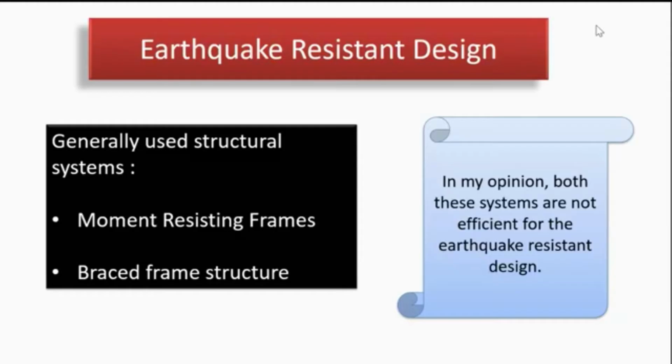But when we are designing the braced frame structure, the bracing we consider in the analysis has substantially different capacity in compression and tension. A member resisting tension in one earthquake cycle will have compression in the reverse cycle.